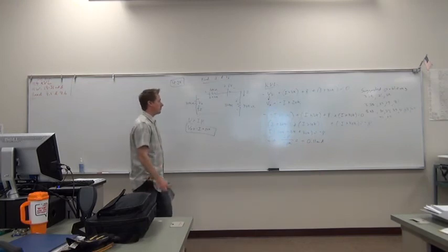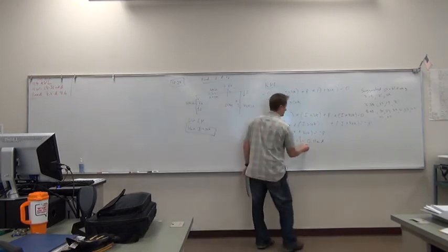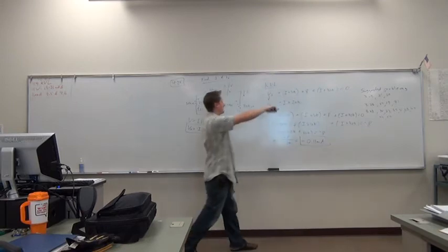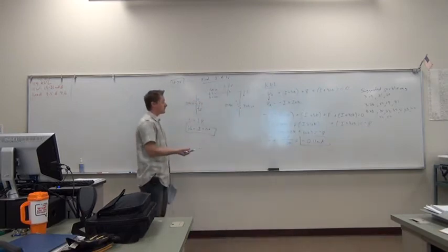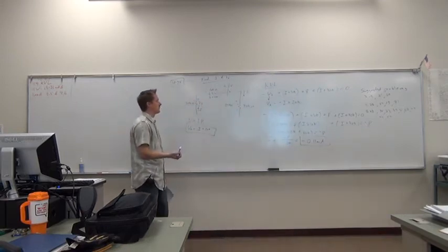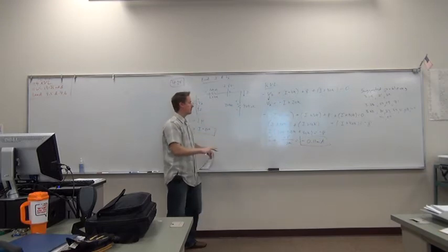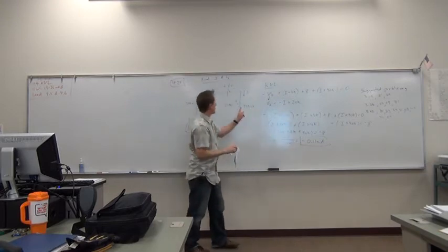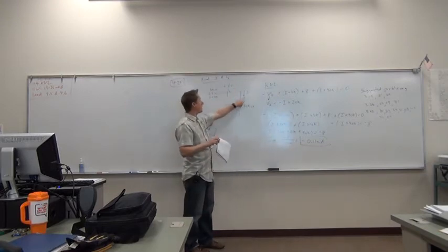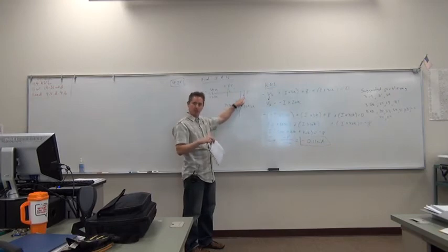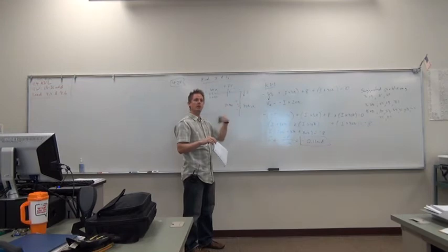So in the end, we wound up with a minus anyway. With all those minuses, we wind up with a minus, which tells us what? Not passive. That the current's actually flowing this direction. But this is still the correct reference, because the minus tells us that the actual current is flowing in the opposite direction to the way our arrow is pointing. So your reference has no bearing on what is actually flowing.